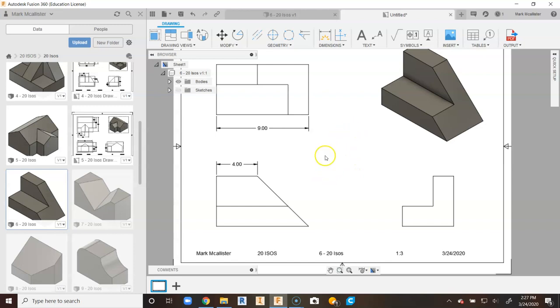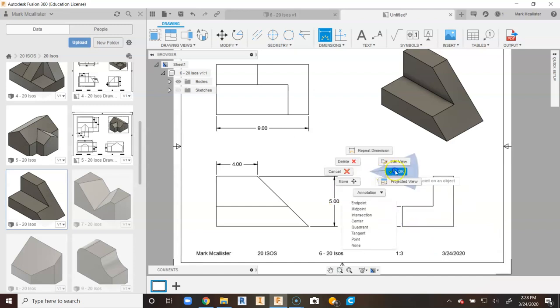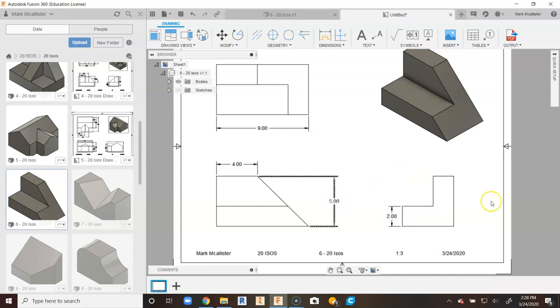So we'll now place the height dimensions for the object, and the question that we have now for the height dimension is, can we place from here to here and drag over and this doesn't look like part of the object? We can go ahead and say yes in this case. So we'll go ahead and place that 5 on the front. We'll say OK, and we'll go ahead and place our location dimension for this smaller vertical line in the side view. If by chance you thought we shouldn't have placed this here and you placed it over here on the side, again, you wouldn't necessarily be wrong. You're just doing your absolute best to always have adjacency for the views.